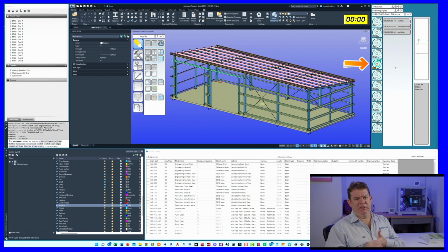They are stick assemblies, welded frames, and welded components, which at the moment is on an A1 sheet, but we think that would be better served to make that an A3 sheet, because it's really about doing welded componentry and brackets that probably don't need to be on an A1 sheet, unless we think that there's a lot more detail that needs to go into those welded components.